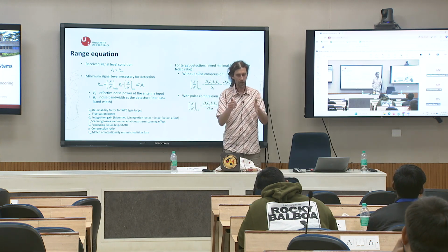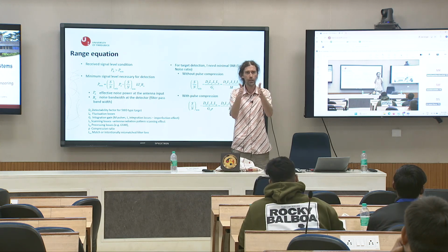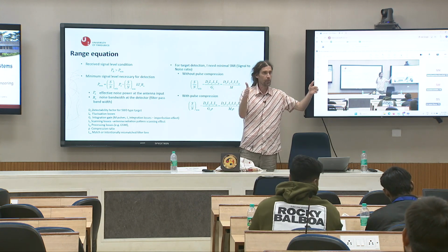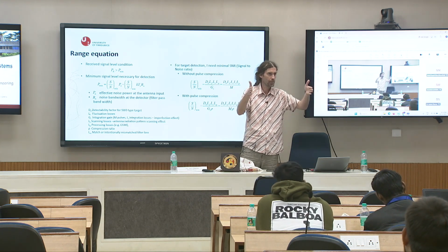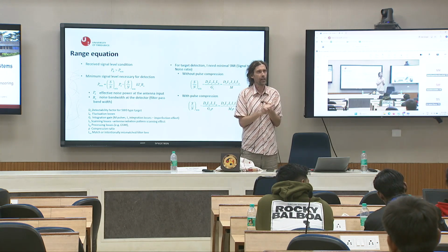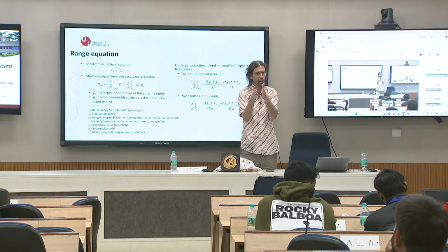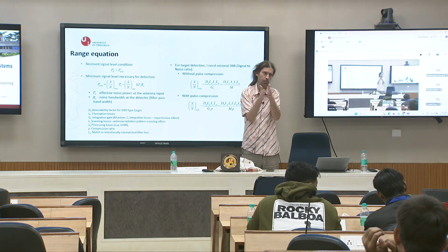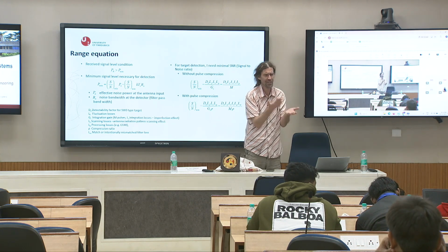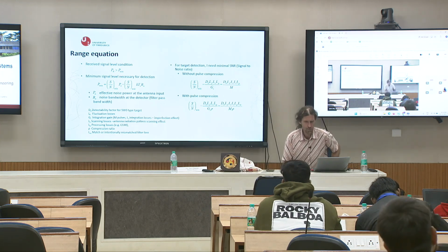Because imagine if I have 1 megahertz and some amount of noise, if I extend it to 2 megahertz, noise will be doubled. Why? Because the bandwidth is doubled. It is independent. So don't think that if you make the bandwidth narrower you will limit noise. Yes, you will limit noise, but you will also limit your bandwidth. So there is no win-win situation about noise. Noise is always present and always will be in the whole bandwidth.